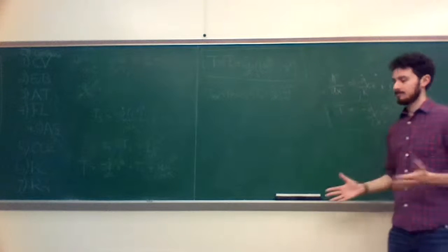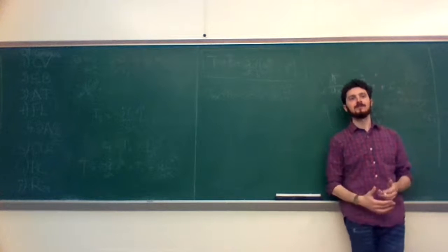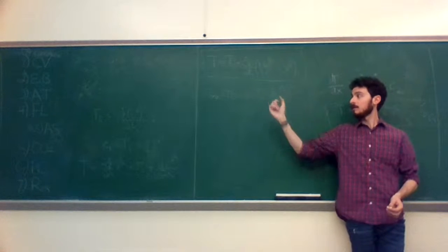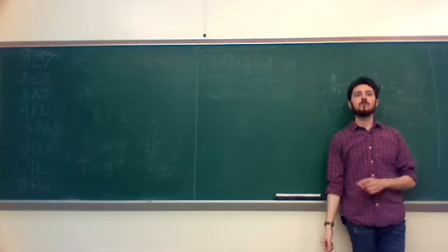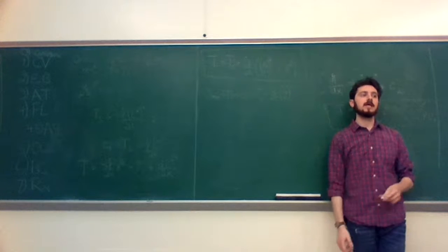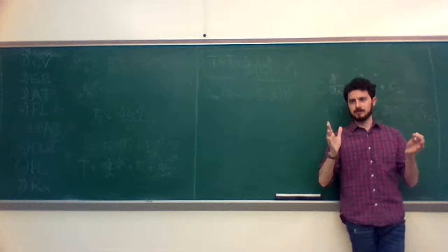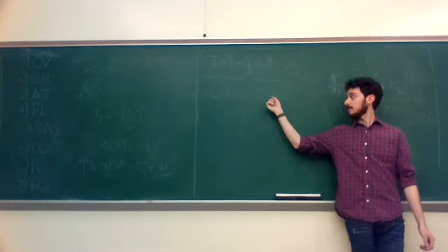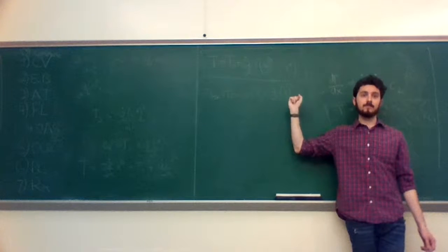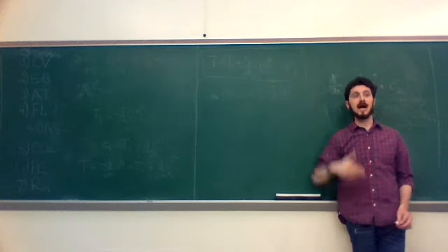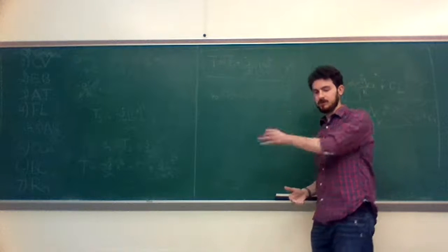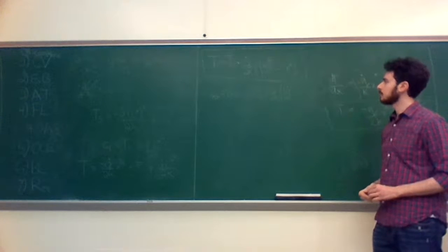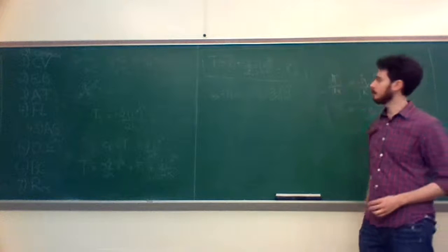The interesting thing though is length scales in the world: you can double something, you can triple something, but it's hard to make it 100 times bigger. You can make something 100 times worse a conductor. So if you want a really hot temperature at the core, and this internal heat generation is like wires inside of a material, you bring the conductivity down and make a really insulating material. If something's 100 times worse of a conductor, the delta T between the surface and the center is going to be 100 times hotter. Is that true, right? K is on the bottom, so you decrease K, you increase your temperature.